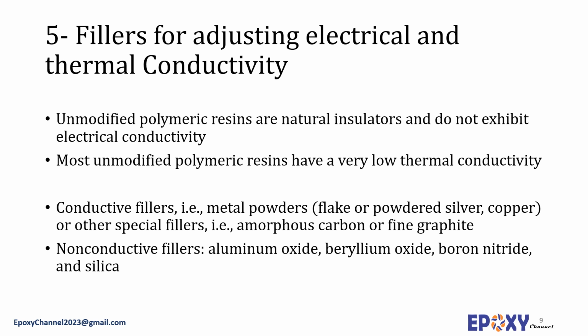Therefore, aluminum oxide and copper fillers are commonly used in thermally conductive epoxy systems. Titanium or beryllium oxide also provide a degree of improvement in thermal conductivity to epoxy systems. Magnesium oxide and aluminum oxide have also been commonly used for this purpose, although the degree of improvement is not as great as the fillers discussed earlier.